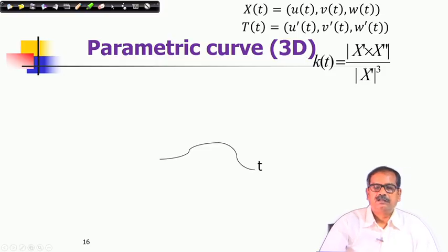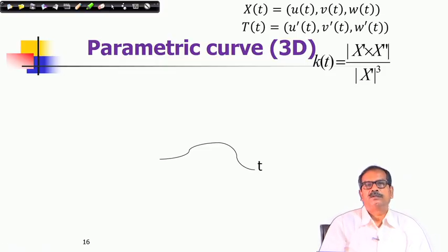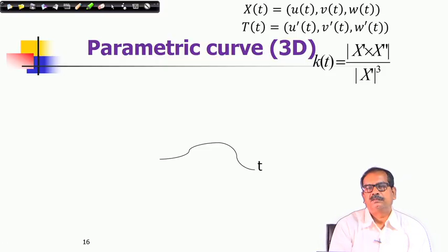So, now we will be discussing the parametric curve which is lying on a surface. In the previous case we have considered any parametric curve, but with respect to surface let us discuss. As such, if I look at the curve in an independent fashion, our previous analysis or previous representations are all valid. We represent it as a parametric curve representation of 3 functions of parameters for x, y, z coordinate given as u t, v t, w t.